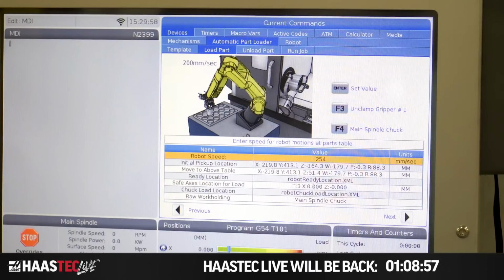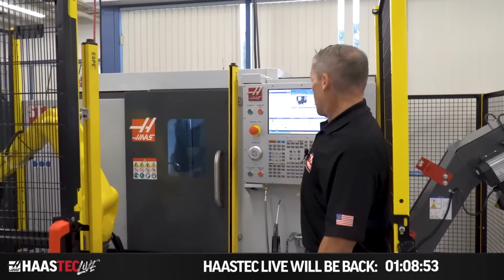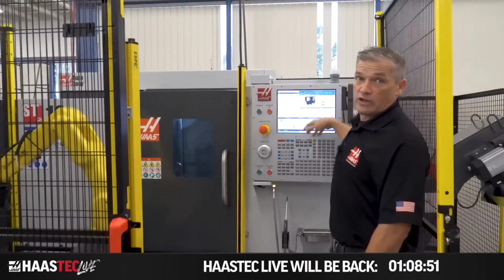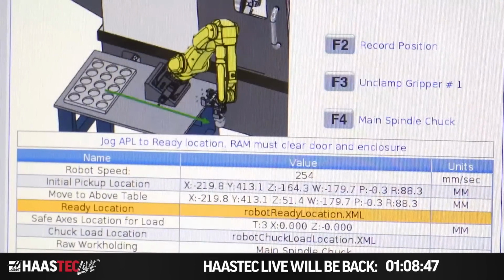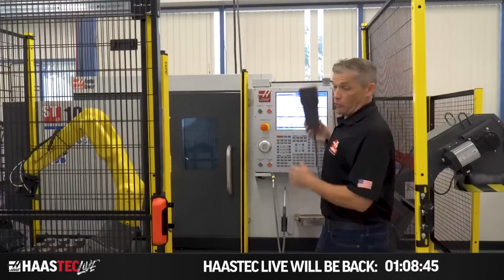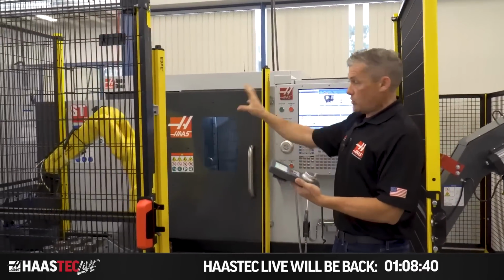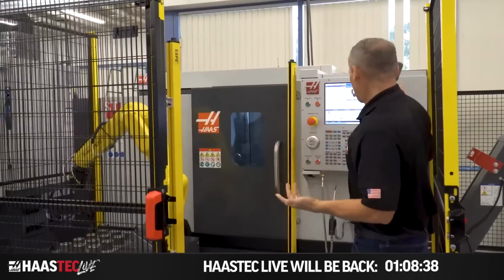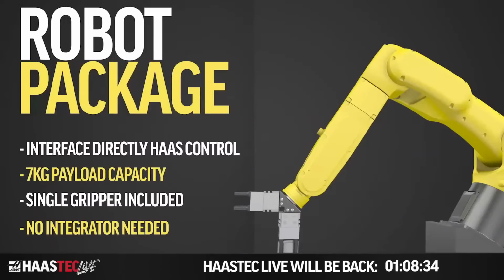And the beauty of it is when it comes time to programming the robot, all of that is handled through the Haas control. We use a series of menus in our familiar VPS system, and through those menus, you control the programming of the robot, and you also jog the robot with our remote jog handle, which has been updated to control the robot. So just a fantastic package and a really easy entry into the world of automation.